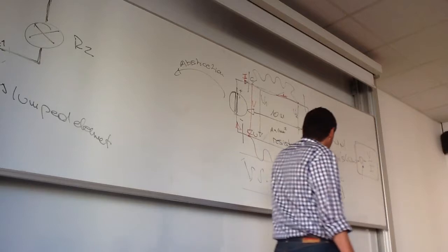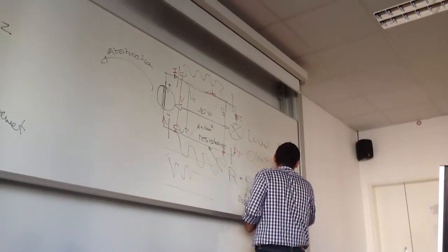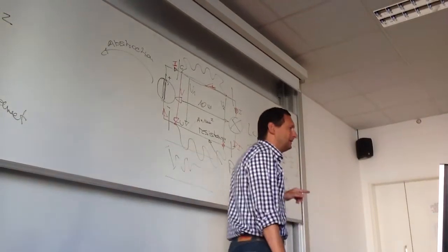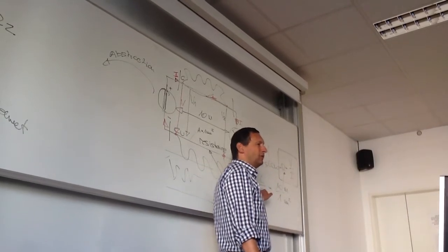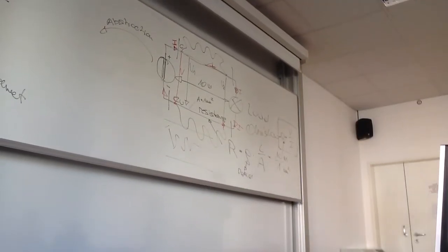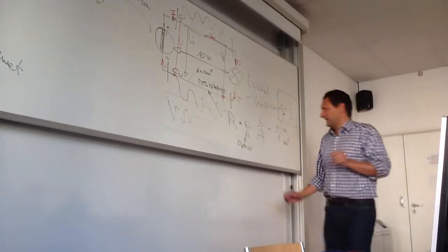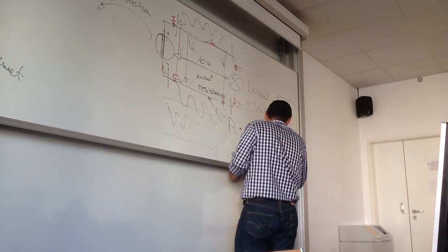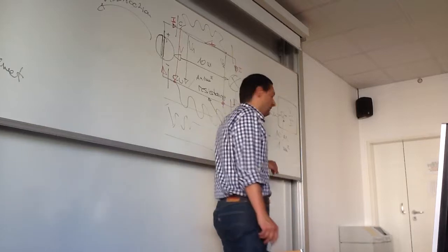So if we do the calculation, we have 10 meters, we have 1 square millimeter, and what we are missing here is this rho. This is the specific resistance related to the material. This only depends on copper. And for copper it's 1/75 or 57.